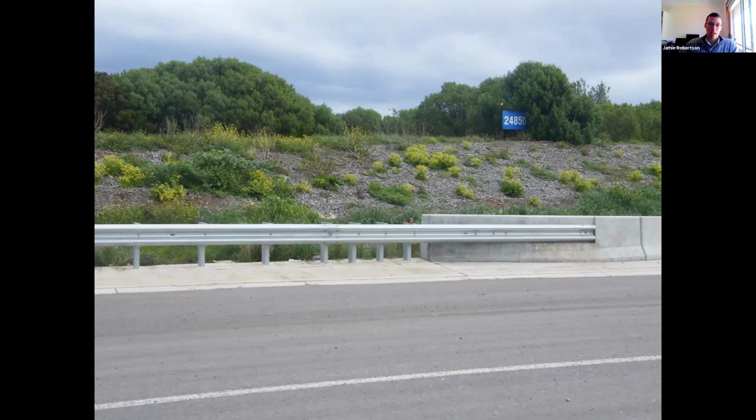Now, if it hadn't been stiffened up and a vehicle impacted that guard fence in advance of the concrete, it would deflect, and there'd be a risk that the barrier would pocket at this point, and the vehicle might snag on the end of that concrete system. Now, this is a Victorian example. In New South Wales and some other states, the standard arrangement is to use a thrie beam, and there is a typical detail in each state on how best to go about this.